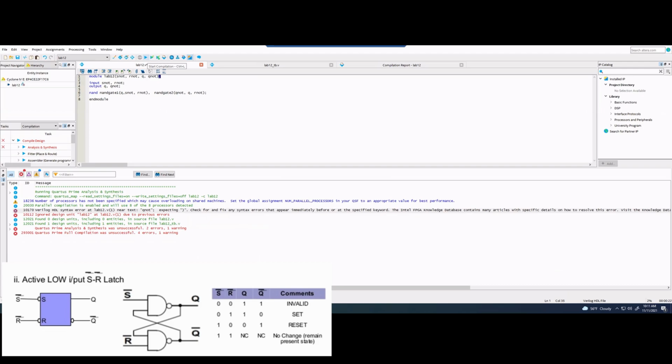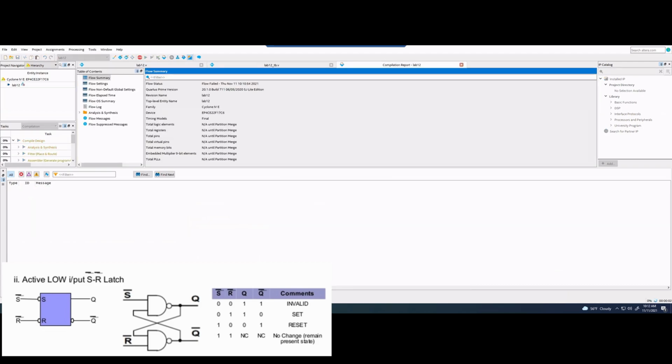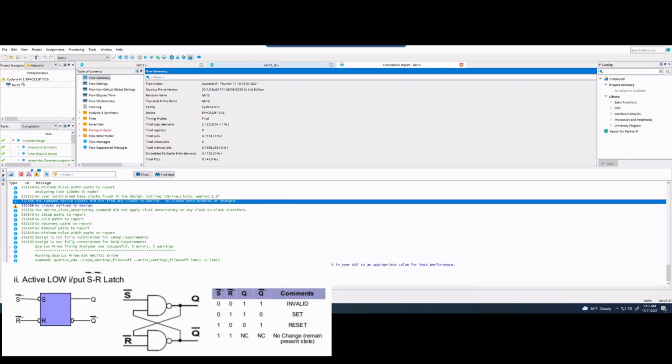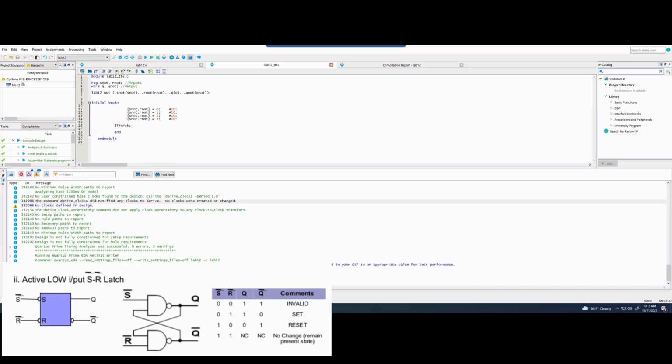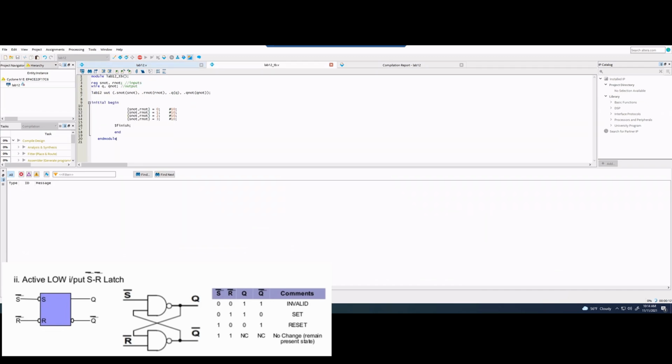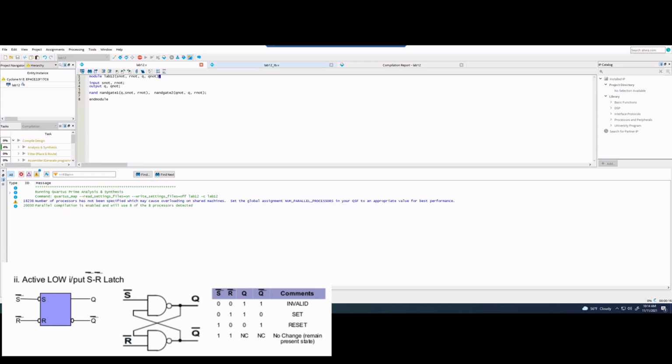We're gonna hover over start compilation again. We're gonna click yes so that we overwrite the bad code, and now it's gonna start running our tasks again. Once that is complete, we have to go into our lab12_testbench file and start a compilation for the test bench file. So start compiling this. That way we have both the lab12 and lab12tb compiled. Don't know if that's 100% necessary. I think it compiles both of them at the same time when we compile just this one. But just to be safe, I'm going to compile this one separately as well.